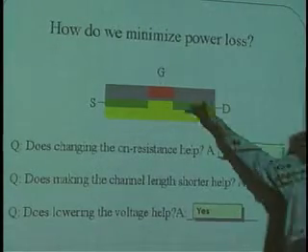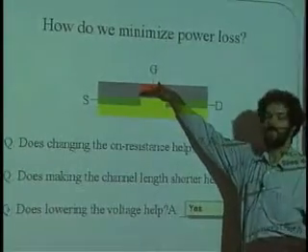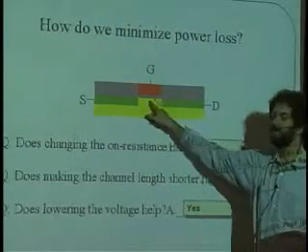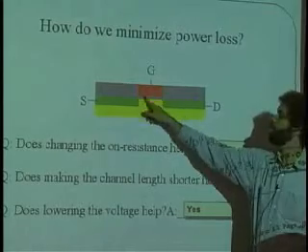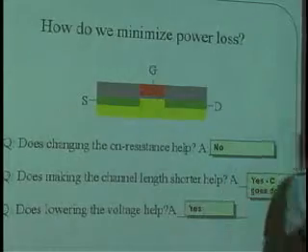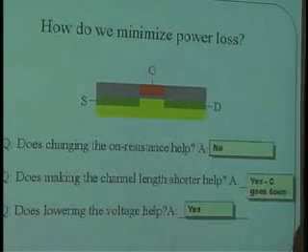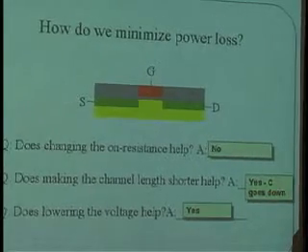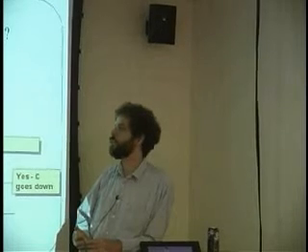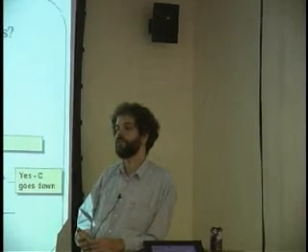The capacitance, remember, is formed by this being one plate of the capacitor, the glass in the middle being the insulator, and the channel being the other plate. And so the size of the bathtub will go down if we shorten the channel and make this less big. Yeah? Do you get into more leakage problems as that gets smaller and smaller? Absolutely true. You bet. Yeah. But usually the leakage here is so good that you don't need to worry quite so much. Mostly the length of the channel is limited by how accurate the photolithography can be to make the channel in the first place without shorting it out.